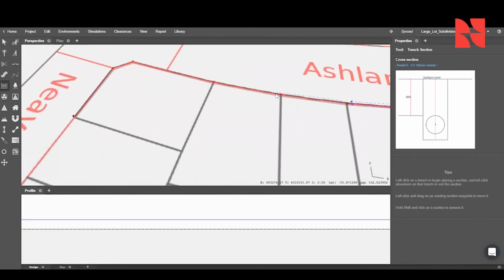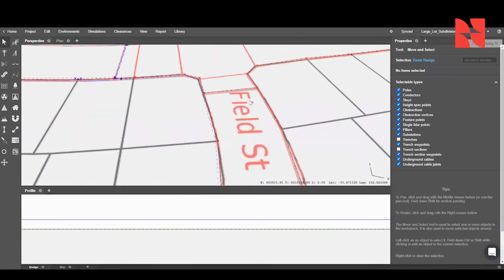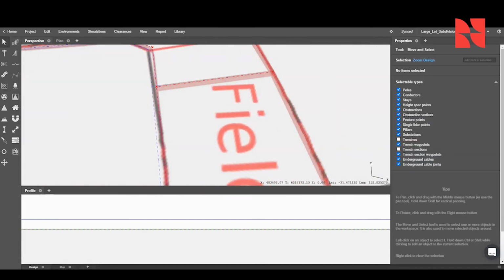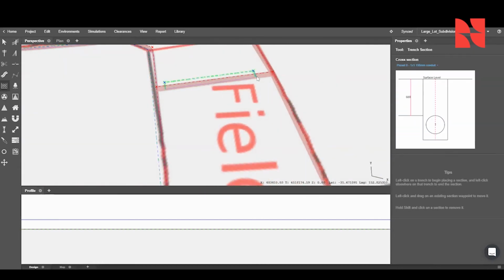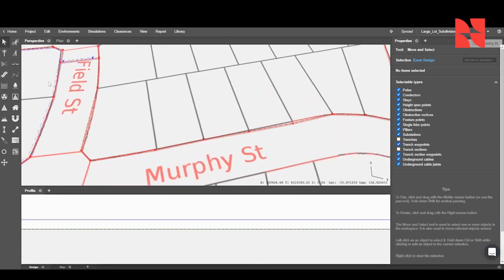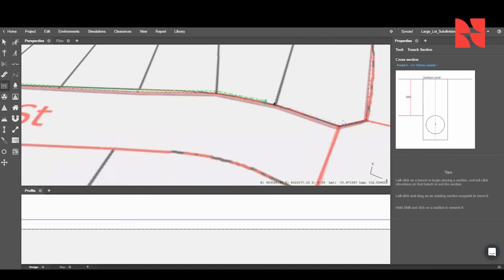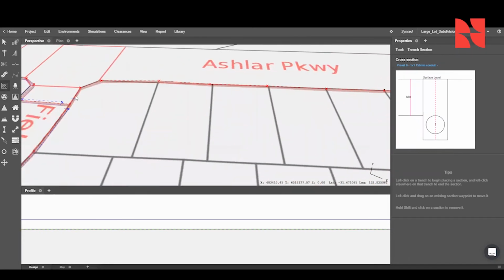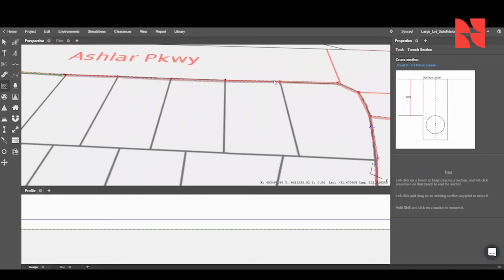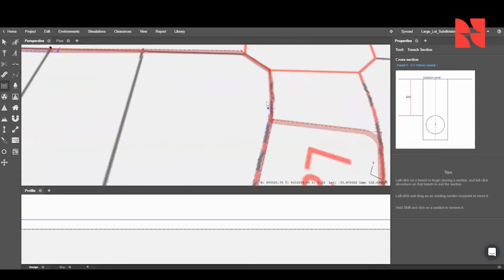Later on, we can actually specify the actual section that's going in that trench and change the placements of the cables accordingly. Adding in the sections this way also allows us to have separate sections between each pillar. This is so later on, we can specify that the section between pillar 1 and 2 might be a 2x2 conduit, for example, while the section between pillar 2 and 3 might only be a single direct buried cable.